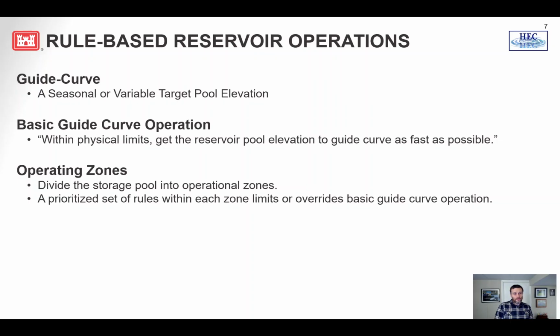So basically there's a handful of things, but to start with, you have a guide curve, and a guide curve is just really the target where you want your reservoir. This could be simply the bottom of flood control, so it could be the same elevation throughout the year. It could be seasonally varying, so maybe throughout the year you have a different target. But guide curve is basically where ResSim wants the reservoir to be. It's kind of like the goal, so it's always trying to get to the guide curve. So that's one key parameter that you want to think about when you're thinking of ResSim.